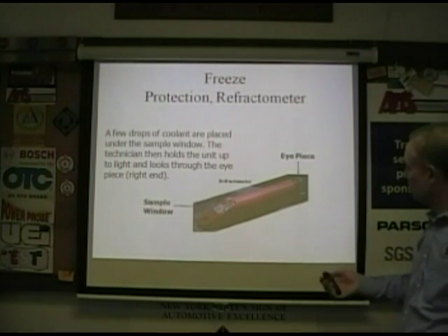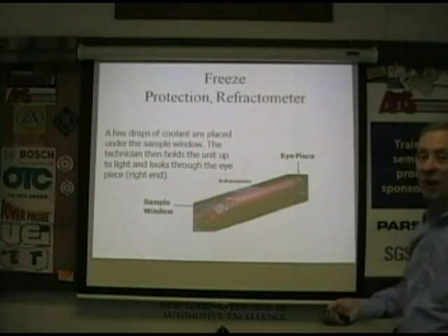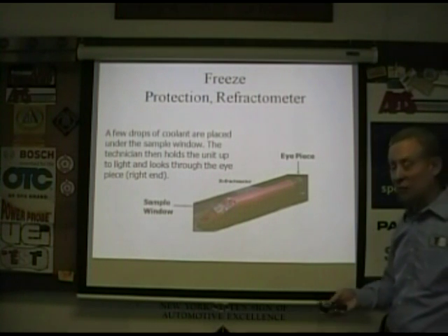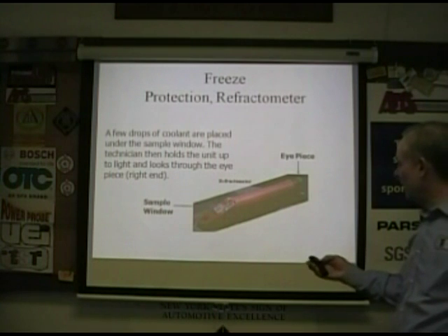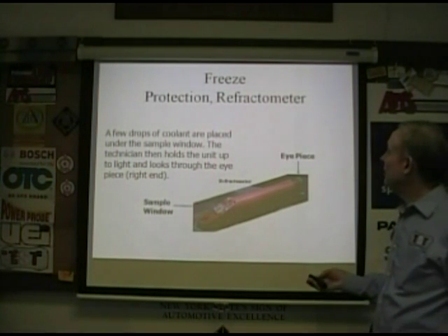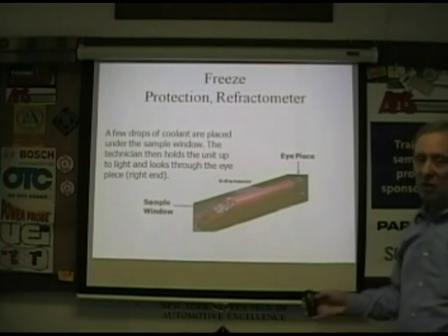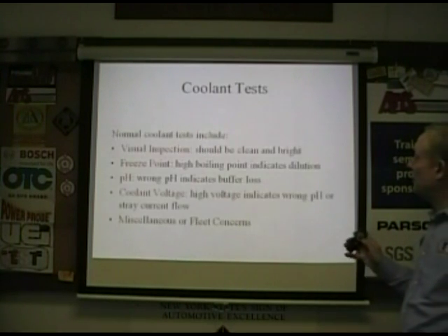One of my favorite tools, a refractometer, for testing your coolant or actually your acid protection for a battery. Very accurate, maintains its accuracy. Way better to use than those ball things, that's for sure. Better than a hydrometer, much better than a hydrometer.